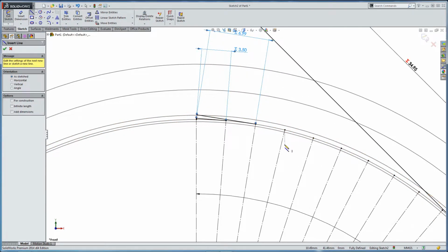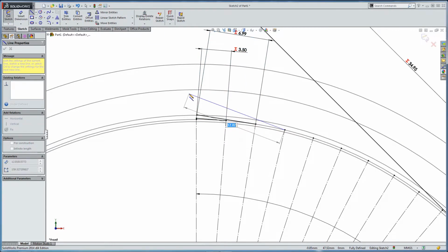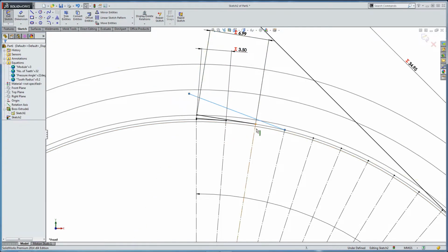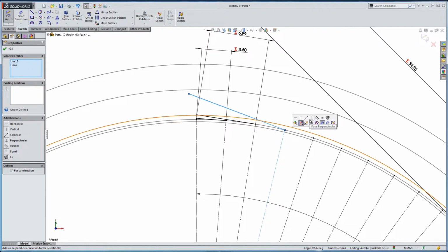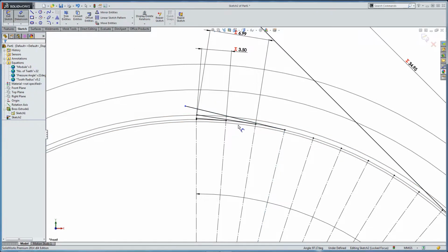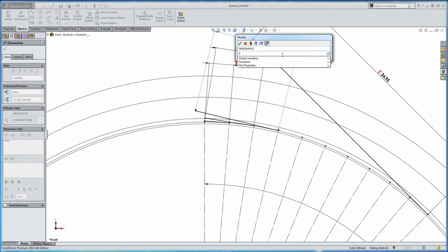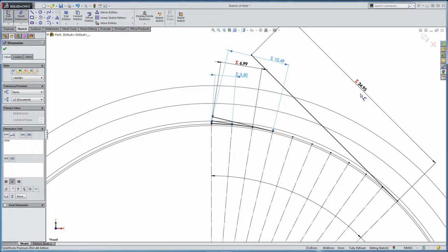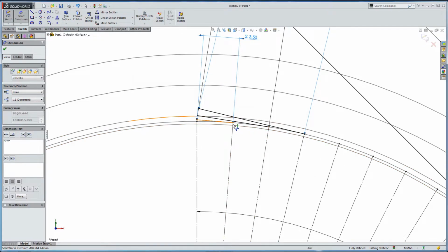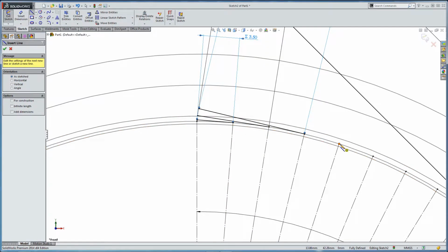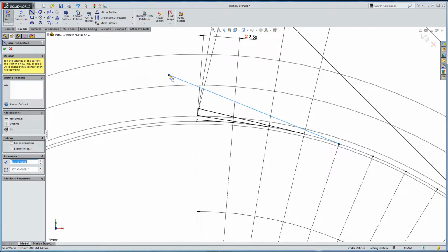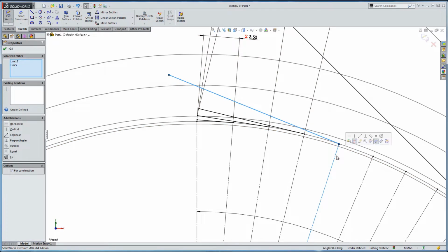So we do this again to the next line. This is perpendicular again, or it will be. We select the 2, make them perpendicular, and then we dimension this new piece of geometry equals the initial dimension, this time with 3 times the distance, so times 3. And we're going to build this up along each of these angles. So we're just building some base geometry.